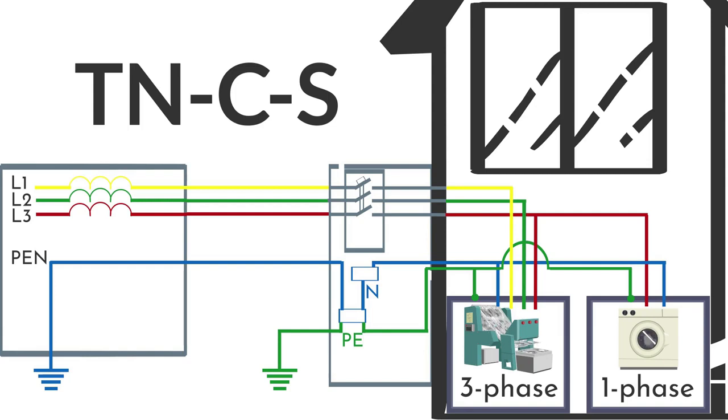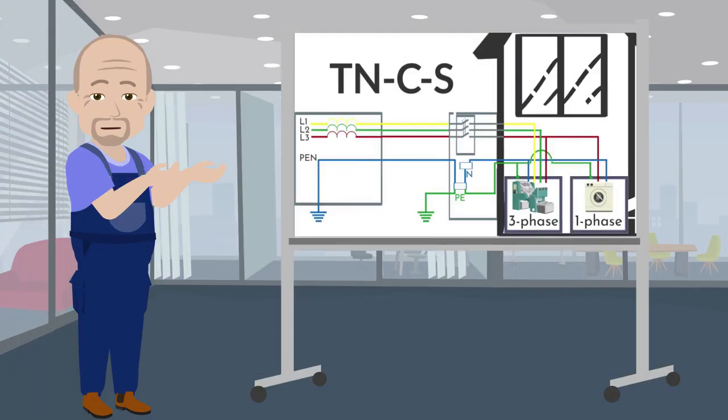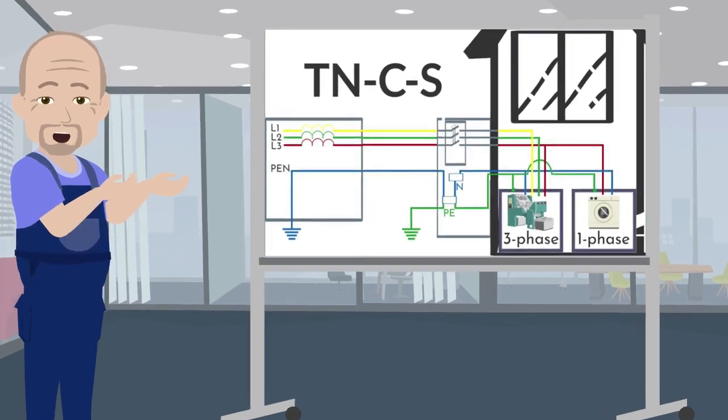The disadvantage of this system is the formation of hazardous voltage in the PE conductor and consequently in all electrical envelopes, which are connected to it, in case the PEN conductor is damaged between the house and the power source. Therefore, proper PEN conductor protection along its entire length and grounding at the main ground bus are required in this system. The advantages of this system are its low cost, reliability and zero breakdown protection. For these reasons, the system is preferred for residential house use.